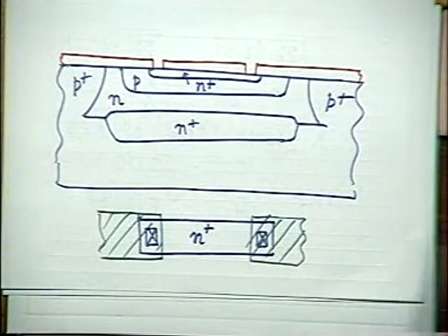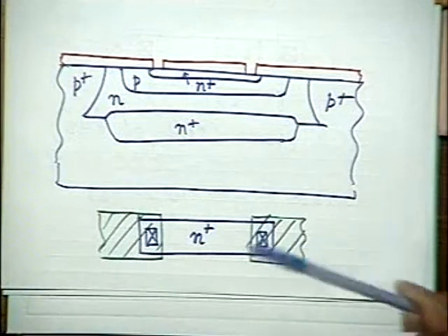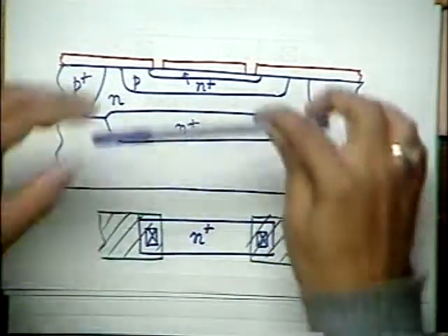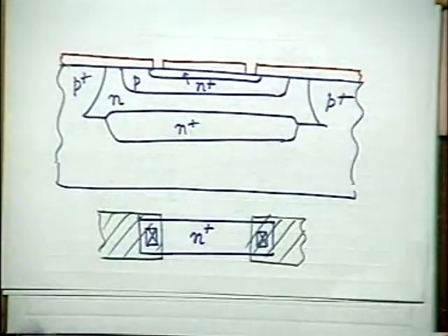A beautiful transistor exists inside. Along with that resistance which I have realized, there is a very beautiful transistor, vertical junction transistor. This is called a parasitic transistor. I have realized a resistor, but along with that, unfortunately, a transistor has come as a gift of God. But this gift may not be a very good gift. It may pose some problem.